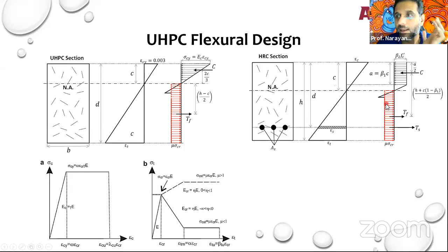And that is where design will have to come in, along with developing a new material, in order to get the complete benefit of this material. Otherwise, we will do a compressive strength test and tell everybody that I have 180 megapascal concrete. In actual design, that will not show up at all. So these added advantages should also come in to make the best use of these materials in design.